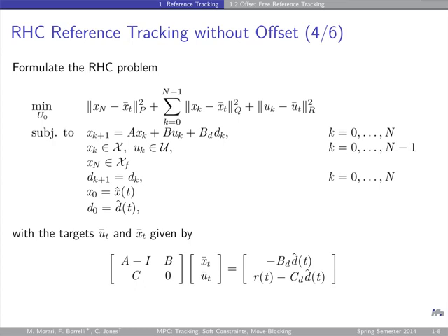The other problem is, say in output constraints, let's say the pressure for some reason, something failed, etc., exceeded your limit. You cannot have a controller that says, pressure exceeded limit, don't know what to do. Therefore, you need a patch. So you need a patch that, okay, if the pressure exceeds the limit, then do this and this to get it back into the limit. So then you have to patch up your MPC controller, which you have designed very carefully, to deal with those abnormal situations where the pressure went outside the limit, and how to get it back into the limit. That's not very practical. So you need to have one MPC controller, then patch it for this situation, then patch it for that situation, etc. So that's another disadvantage of hard constraints.